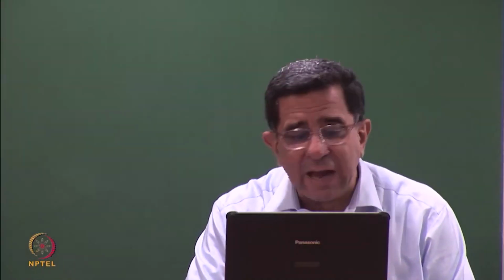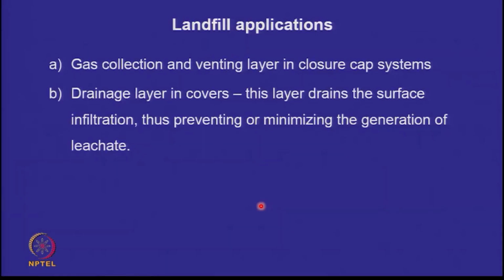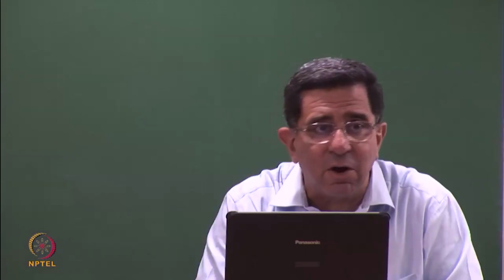They are also used in gas collection layers in landfills, and they are also used in drainage layers of covers, just beneath the topsoil. You can't use them in the leachate collection layer because the rubber may react with one or two of the constituents of the leachate, which may cause a problem.